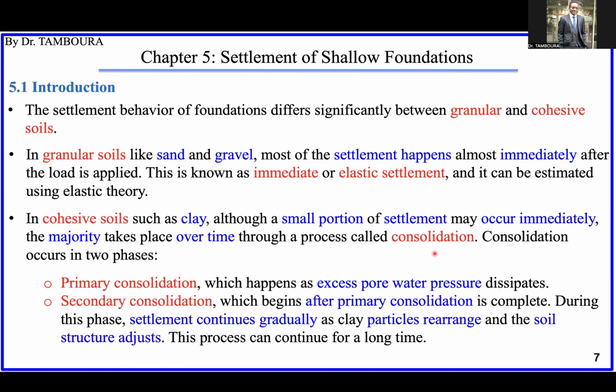And the secondary consolidation begins after all the water in the ground is gone, and then the soil particles start to rearrange. The water that was helping the soil to support the load is gone, so the soil particles now receive 100% of the load.